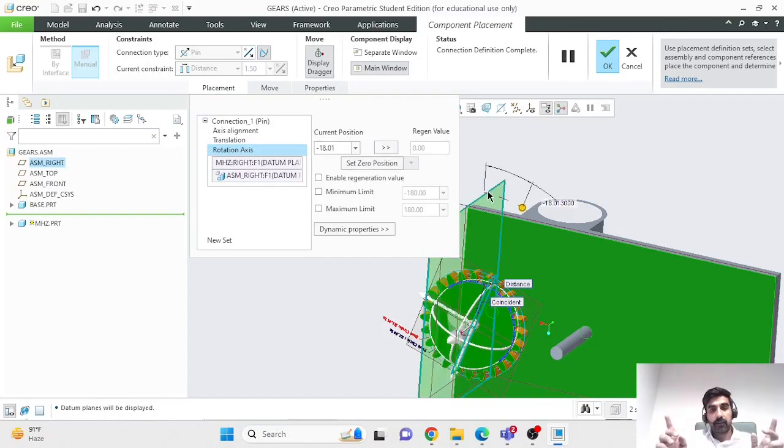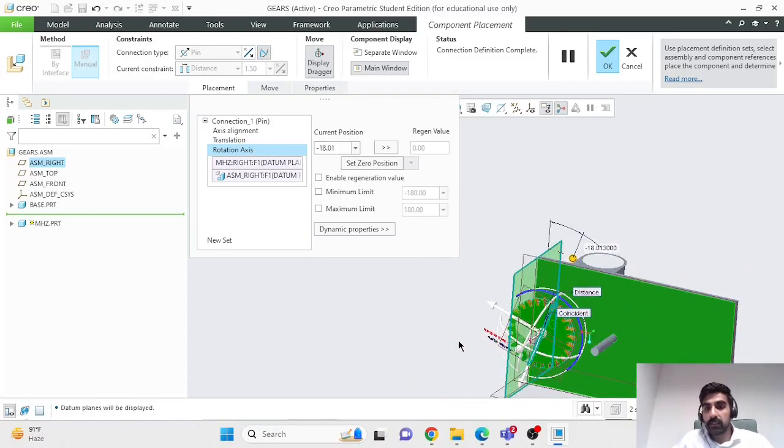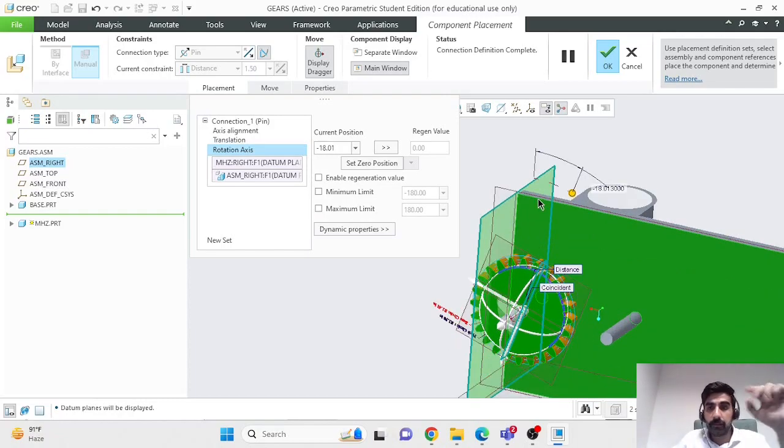And then you can use these two as references, so that the angle between these two planes is allowed to vary between a lower limit and an upper limit. You have selected those two planes, and it doesn't really matter which references you select, because the limits that we define, the minimum and the maximum limits, you will choose based on your requirements, and they can vary depending on the planes that you choose.